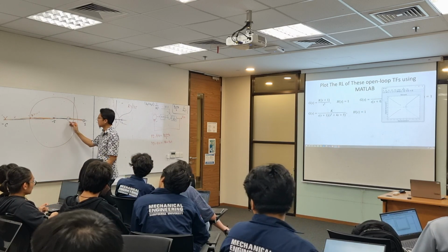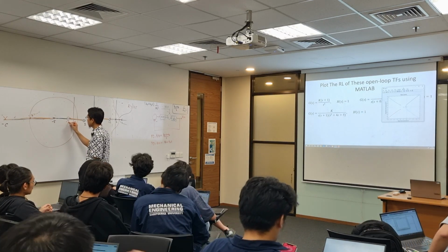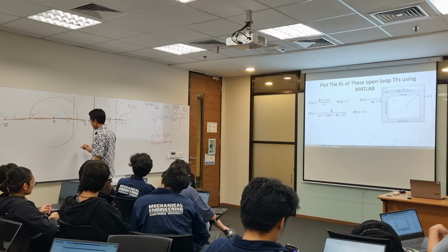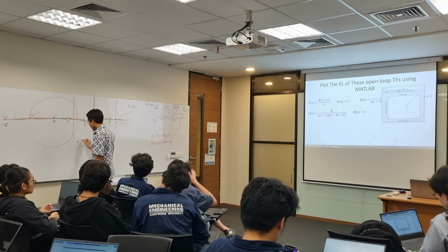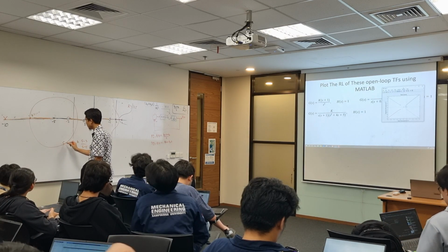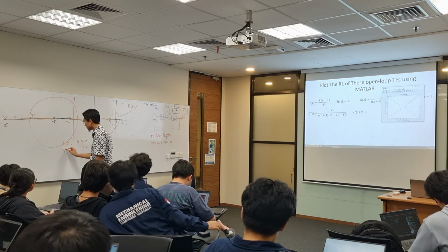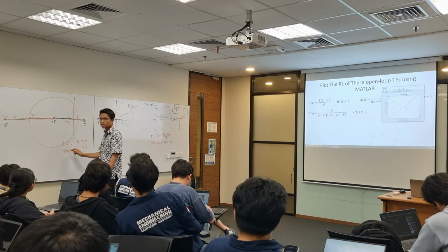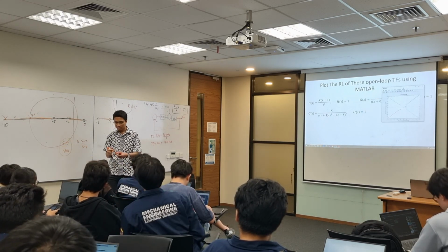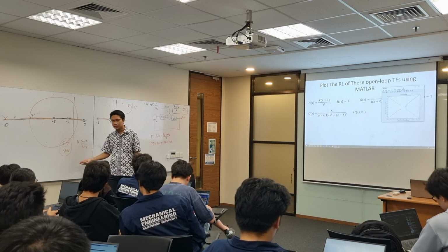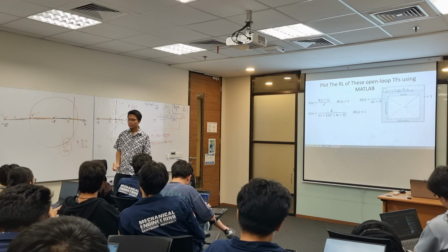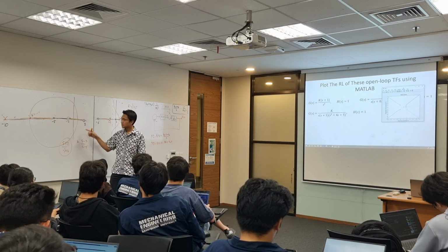Let's say I put the 0 in here to be -2 and another pole to be, let's say, -10. So previously it is k (s - 3). My controller will be (s + 2) over (s + 10). You try this. I just have my controller to be this one. I don't need to make a design. Is it PID or PI? Just based on the root locus. You can try this using MATLAB. Is it correct or not?